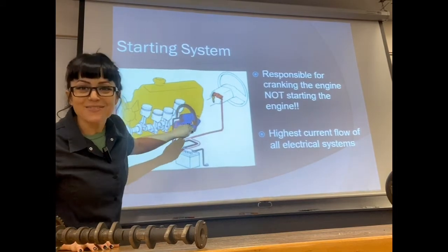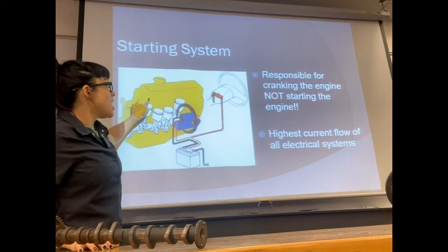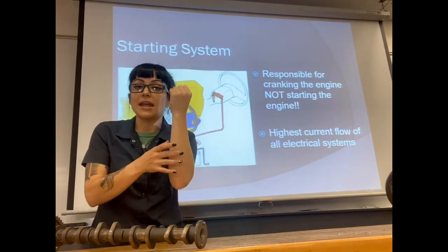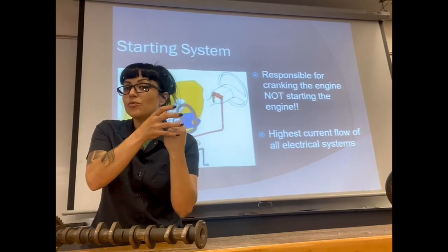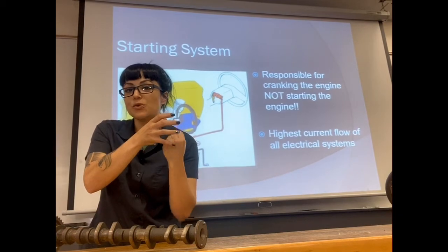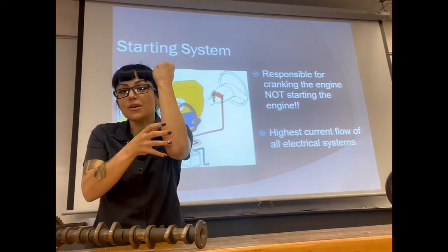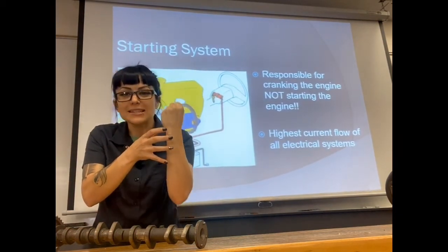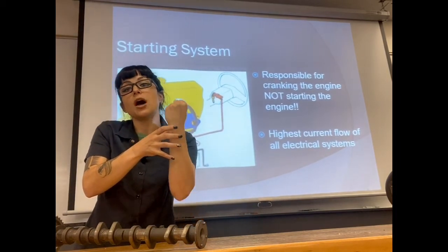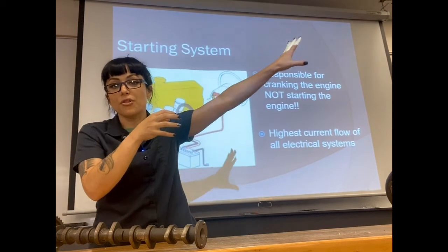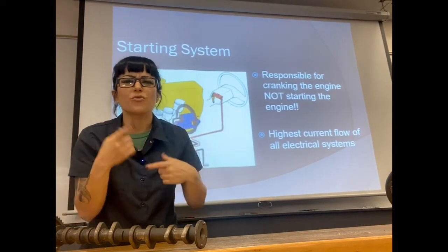Inside of your engine, you've got a bunch of pistons moving down inside of a cylinder, right? It's moving down to suck in air and fuel. It's moving up to squeeze the air and fuel. It's blowing it up, and that's getting the piston pushed down. And then it's going to push up again to release all of those exhaust gases, and then it's going to do it over and over again.